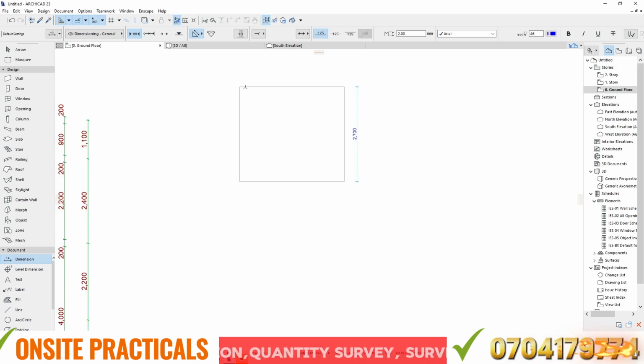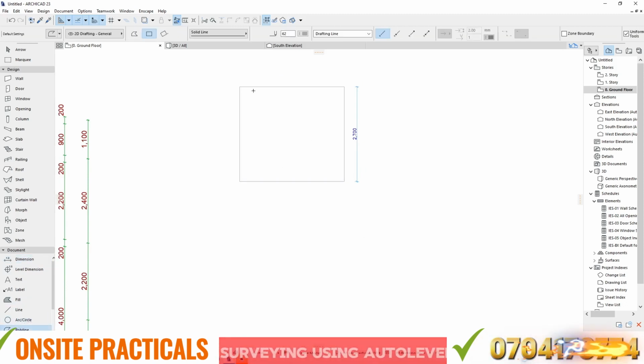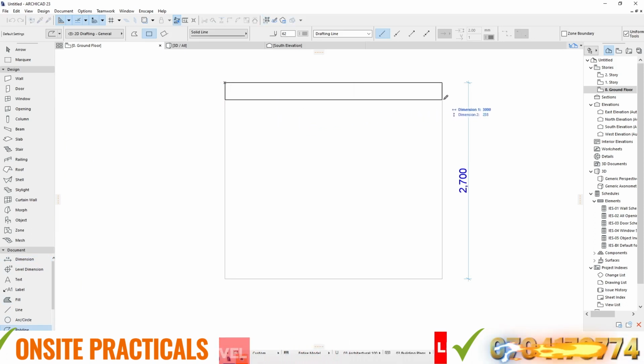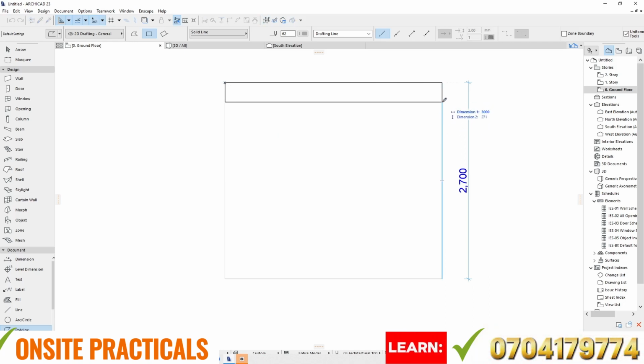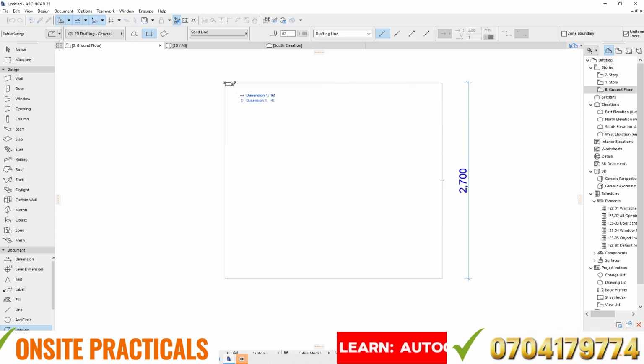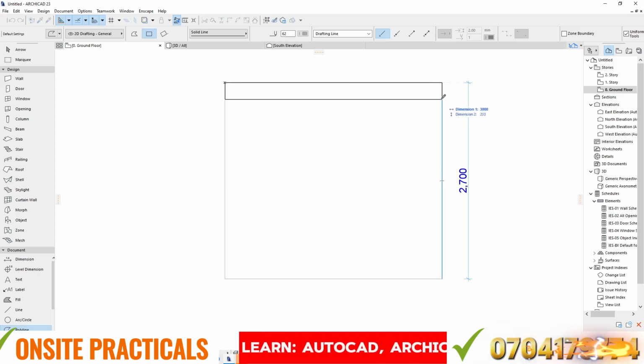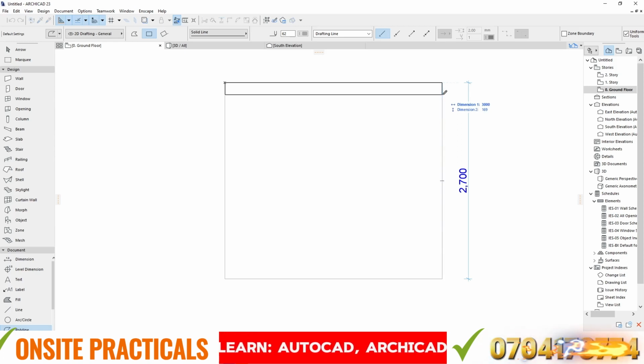So if now I have a slab, when you're doing the slab, you're doing the concrete work or the concrete pour, what exactly is going to happen is that you will have your slab casted downwards, you see, because the formwork or the soffit of your formwork for the slab will actually be on this part, right? So you're going to have here, for example, the thickness of that slab to be 150. You see, so that's the whole thing.